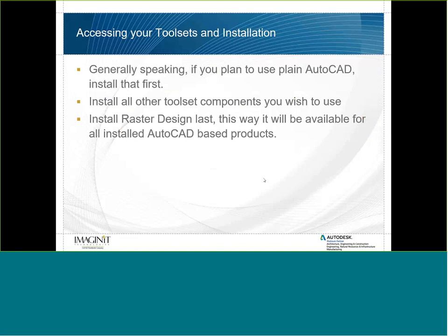The big thing though is that if you're going to use Raster Design for any reason, you always want to install that one very last. The reason why is that you want it to be available for all installed AutoCAD-based products, and if you install it last, it will detect all of the products you have installed and will add the Raster Design tool palettes to every single one of those. And if you miss one, then you have to go back and do a reinstall of Raster Design in order to get that information back into the other packages.